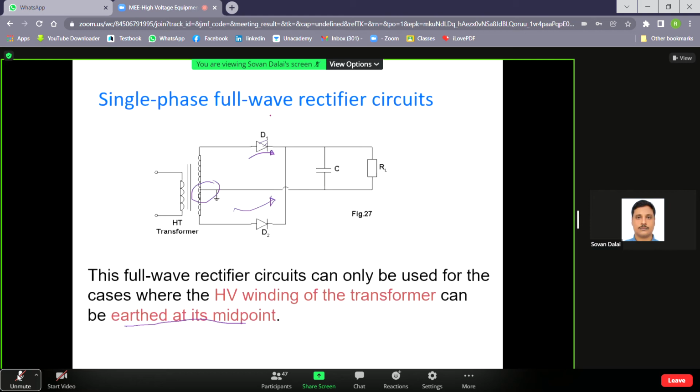But if you use this circuit instead of the single phase half wave rectification scheme, there will be no such question of core saturation. If there is a wide variation of positive half and negative half current, then there is a question of saturation, otherwise not.